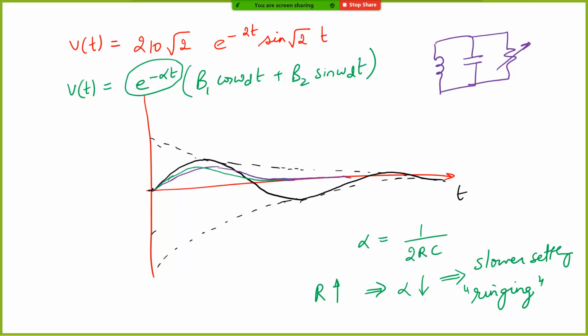If it is a second order system with an underdamped response, then if you take your bike or car over a hump, it will keep oscillating for a long time. A hump in the road is like a step response. So when designing the suspension, you want to make sure that it settles back very smoothly. All these things are used in different systems, just to give you some perspective.